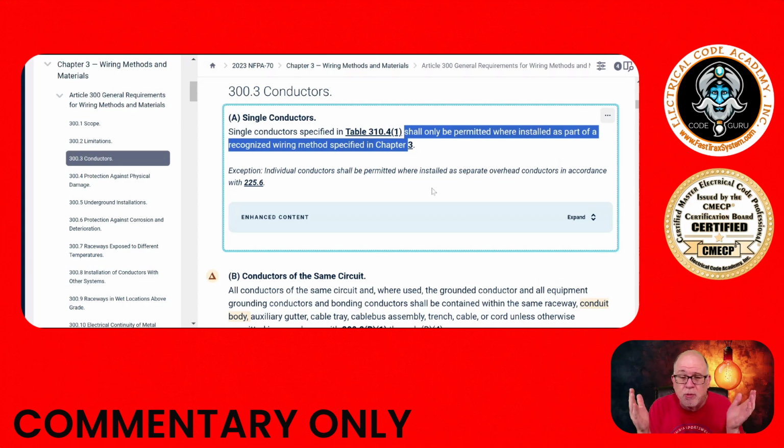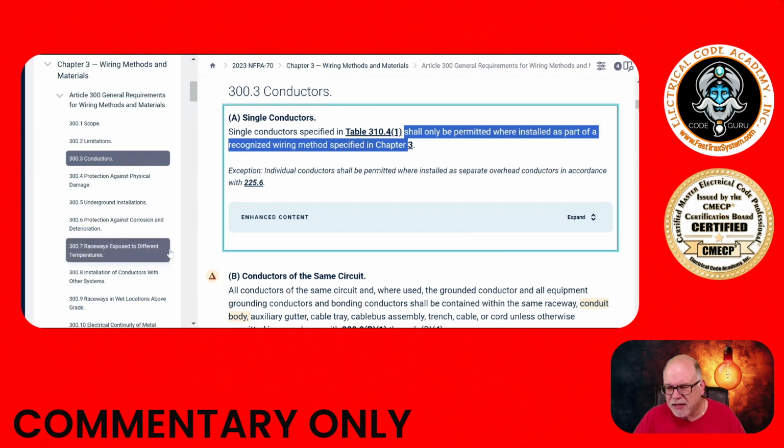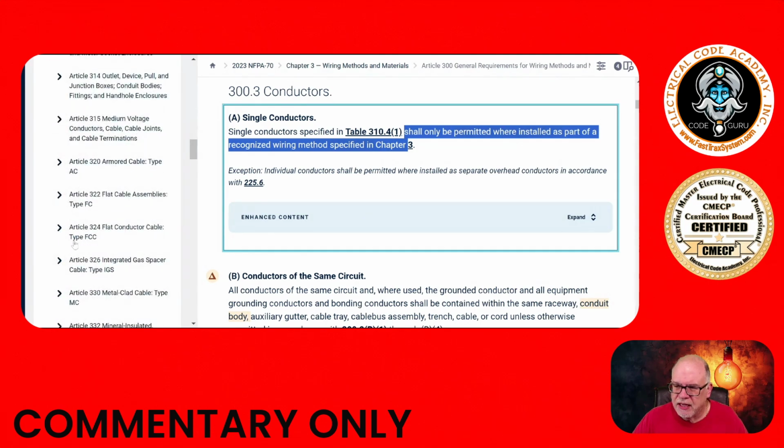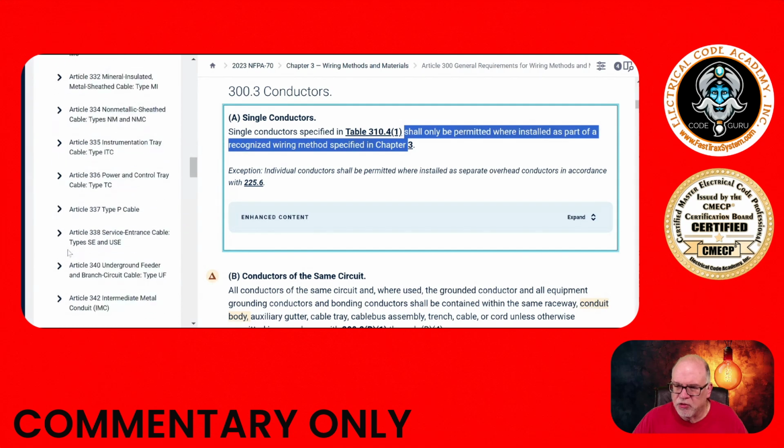Well, you're saying, what about USE-2? Isn't that an individual conductor? Yes, but it's covered under Article 338, and that is specific for USE, and it says that it's rated for direct burial if it has that marking on it. You get me? All right, so lastly is the one that was in question, and that was 340, the UF.